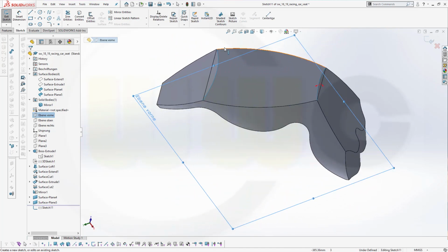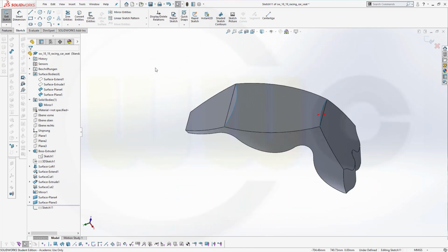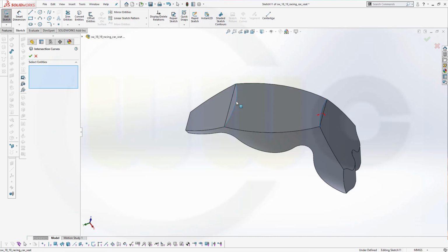And I would like to use the center point of those, and I want to use a spline. So how to get that point here? I could put a point there just to make sure. First I have to convert the center into my sketch, or maybe go for intersection curve. Let's go for intersection curve. Select it, confirm, and select this face and